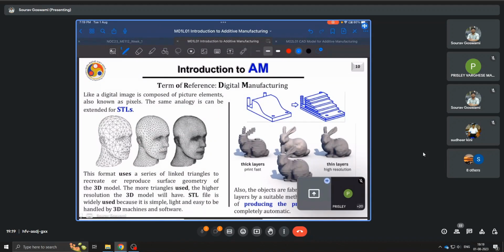People related to the field of additive or working in additive will often hear the term STL. I mean, of course, all of us during our CAD CAM classes have, and it is one of the more commonly used file formats for exporting 3D objects, along with, say, some of the older ones like IGES or STEP. But when it comes to AM, STL is the predominant standard. It has legacy support, and it stands for, well, first stereolithography. That is where, in fact, it came from.